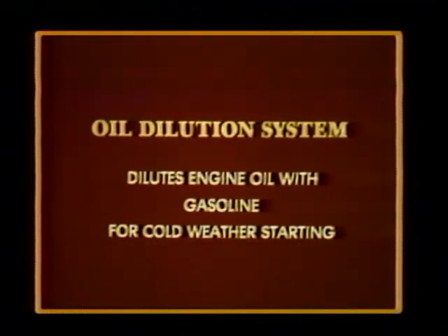Cold weather presents a problem for the lubrication system. In fact, the oil may become so thick that the engine becomes hard to start. To help solve this problem, it is recommended that before the engine is shut down, some gasoline directly from the fuel system be mixed with the oil to dilute it. This diluted oil provides adequate lubrication for starting, and the gasoline will evaporate out as the oil warms up.